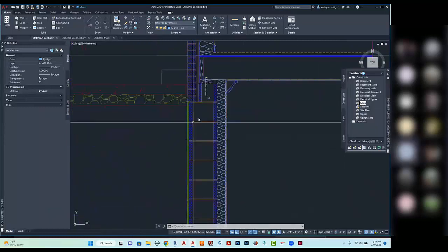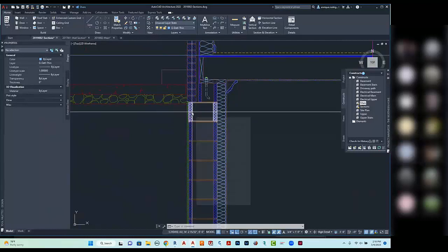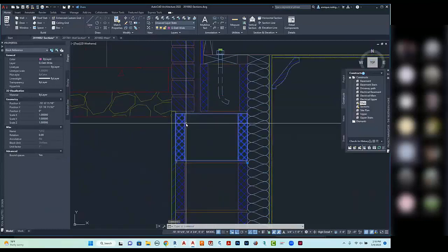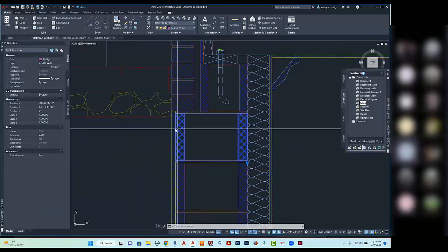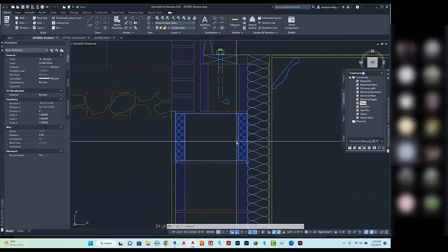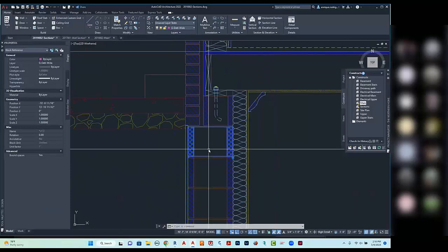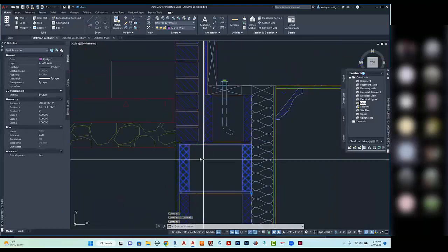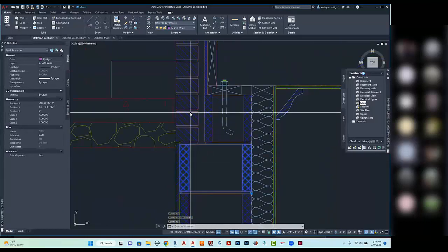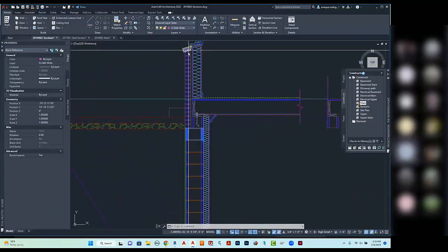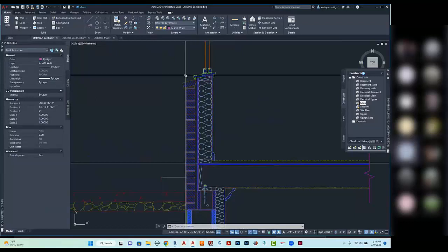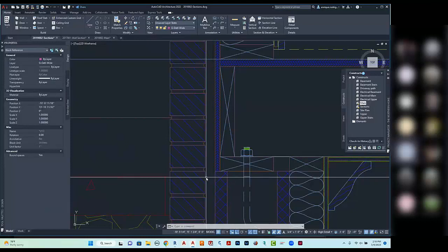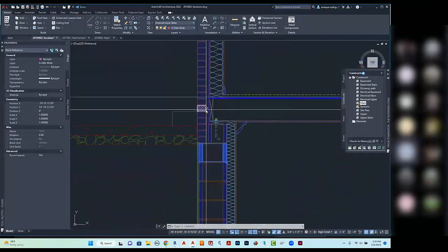Let's go ahead and continue with our wall here. You're going to notice that this is wider than the 8 by 8. So this one's going to be a 12 by 8. Vertical dimension is 8. Horizontal dimension is 12. And the depth is 16. These are all modular dimensions. Now, the purpose for this option that we did was to create a ledge for the brick to rest on when we build that short, roughly 4-foot wall of brick right out the front. Notice there's also a gap between the brick and the plywood, etc. That's an air gap.